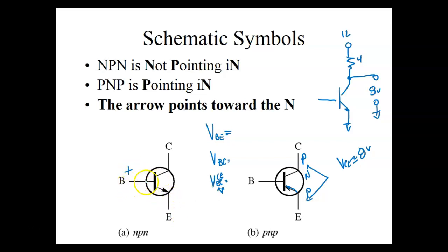And we have to forward bias it. If it's a silicon transistor, to make it start conducting, we're going to need approximately what for silicon? 0.7 volt. If I don't hit that forward bias and get it conducting, then we have no base current, and if we have no base current, basically the transistor is cut off.